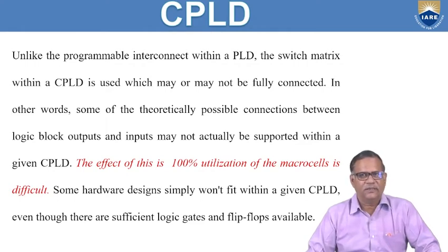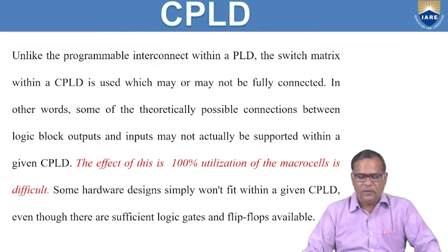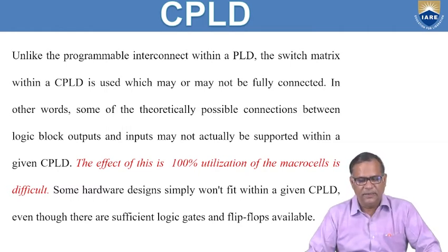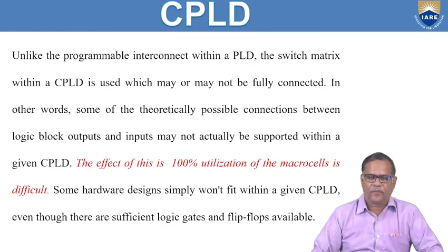So what is the effect of this? 100% connection of macro cells is not possible. So because of that, some hardware designs may not fit in the given CPLD, even if there are sufficient PALs and even if there are sufficient flip-flops.